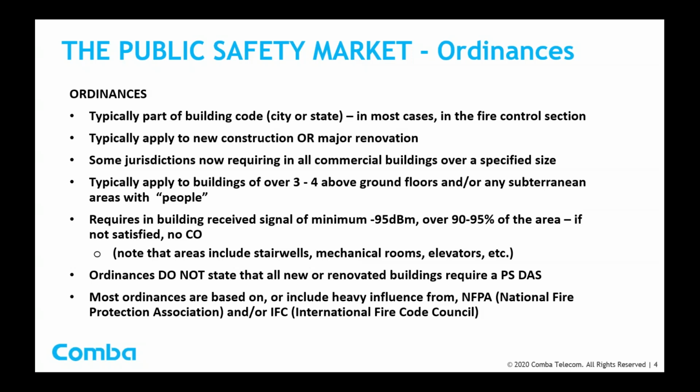It's typically ordinances. Ordinances are typically part of building code, either city or state. In most cases, they're the fire control section of the building code. They typically apply to new construction or major renovation of existing buildings. Some jurisdictions now are requiring all commercial buildings over a specified size, even if they're already existing and even if they're not going through major renovation. Ordinances apply to buildings of 3 or 4 above ground floors or more, and/or any subterranean area with people.